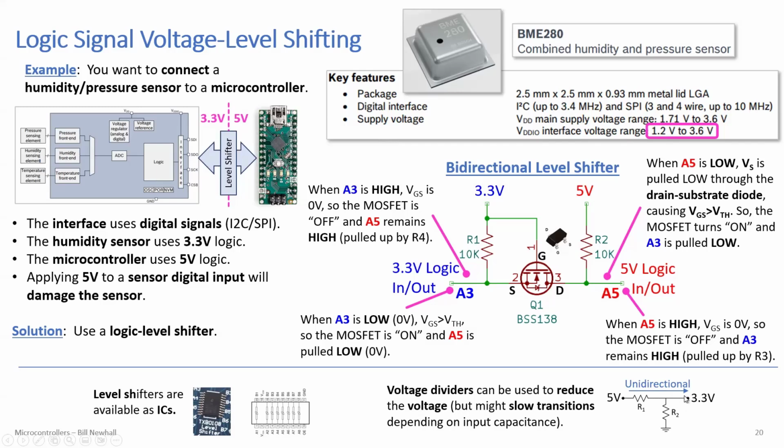The catch is, though, if you have any kind of significant capacitance on the right side here, because you have those resistors, you might get slow transitions because of the RC time constant. Right? You have current going through a resistor charging a capacitor if there's capacitance on the right. So this won't work for high-speed circuits, but it'll get you by for general purpose logic often. So that's a really simple way to do it.